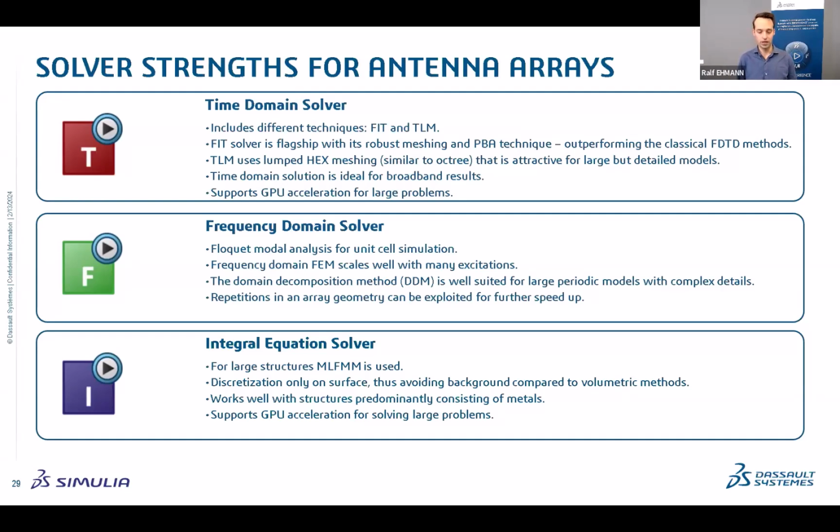Both support GPU acceleration. And then there's the frequency domain solver, which we've been using for infinite arrays for a long time with Floquet modal analysis. But we've also recently introduced the domain decomposition method, which is well suited for large array models with complex details, where we're able to then exploit repeatability within an array geometry to really speed things up. And might I also say, just coming to the finite element method in itself without DDM, with a direct solver, it scales very well with many excitations. Although we would recommend just DDM in such a case.